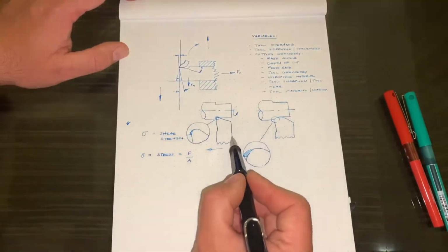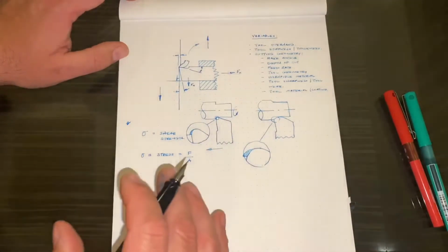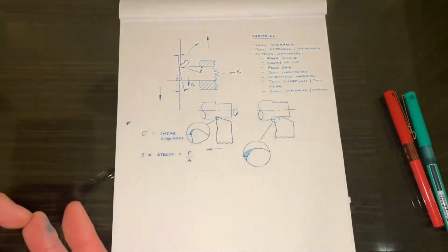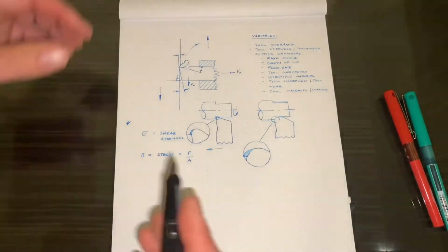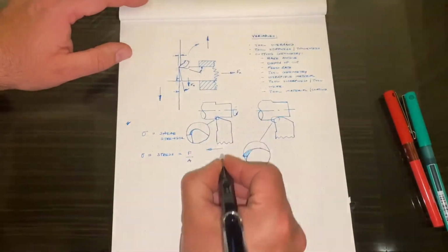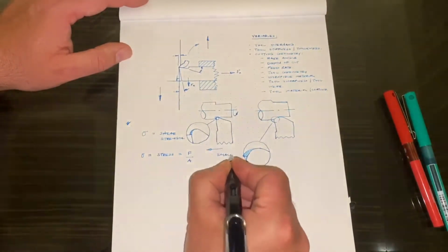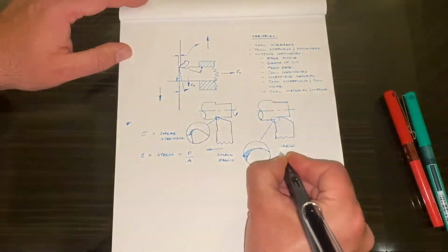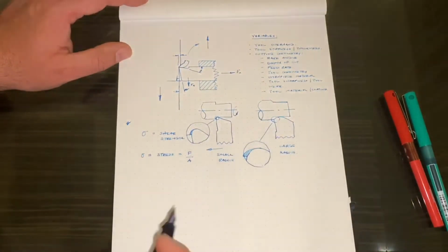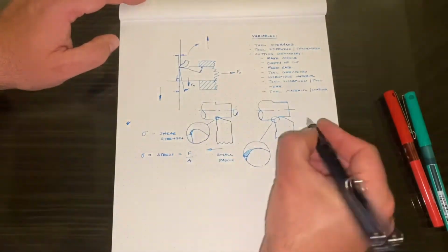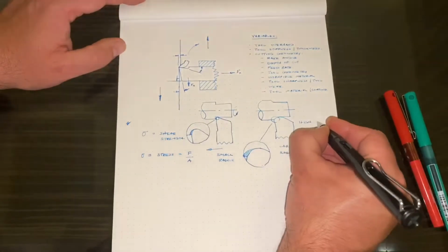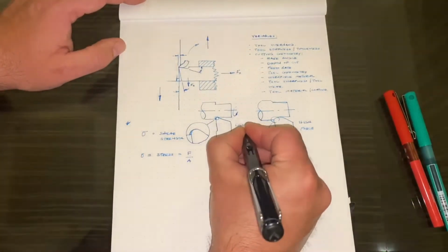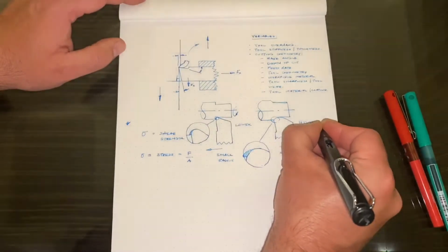if we have the same material in both of these scenarios, with equal machining parameters, so the same feed rate, the same spindle speed, the same depth of cut, then what we find with a tool that has a small radius compared to a large radius is that the cutting forces increase here, so please forgive the writing, and lower force here, so higher and lower force.